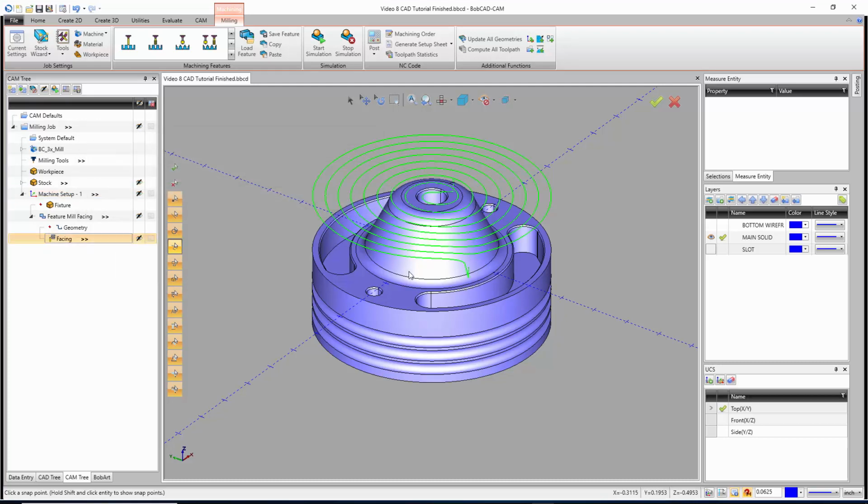And there is our toolpath. And what we'll see is it's already blanked out. We just don't notice it because it did select that final facing feature. I like to blank out the features so they don't get in my way. The way that you can look at your features afterwards is just by clicking on the individual operation of the feature. So if you have multiple toolpaths, you can click on each individual one. All right, now we're going to go ahead and shrink that up.